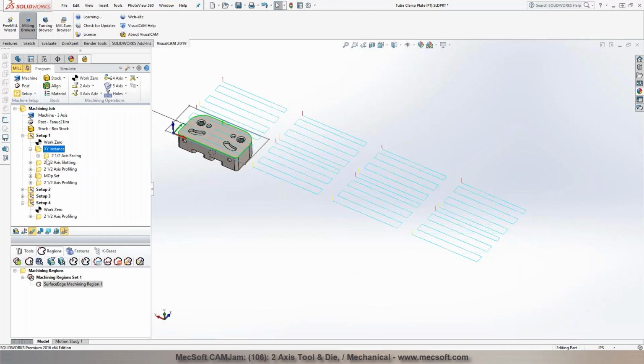You can instance it based on part priority, or based on tool priority. If you do part priority, all the operations will be programmed on one part before it goes to the next one. If you do it based on tool priority, you'll minimize the number of times you have to change tools, because you use the same tool to run all the parts and then go back and run the next tool, right? Yeah. So you can have one instance folder for each tool that you're using.